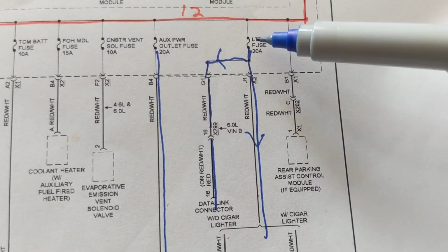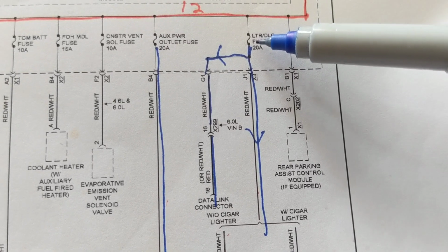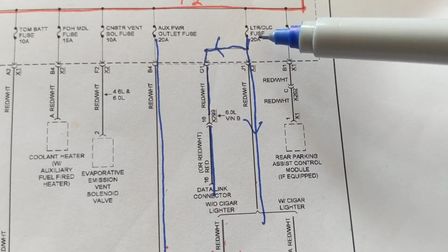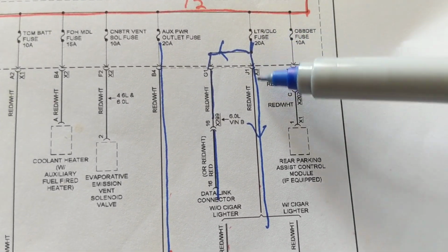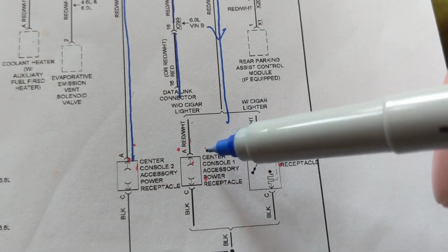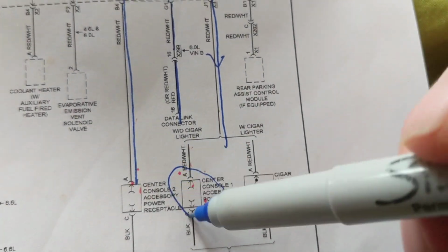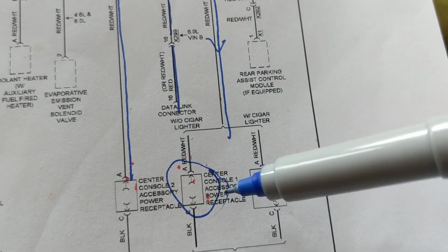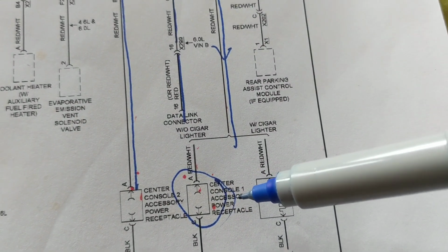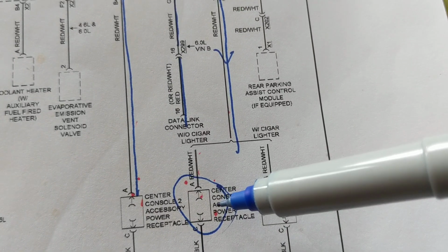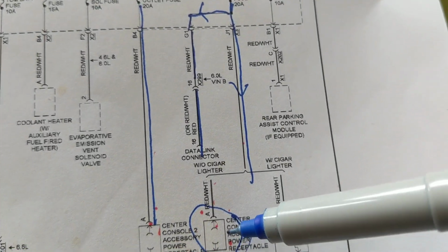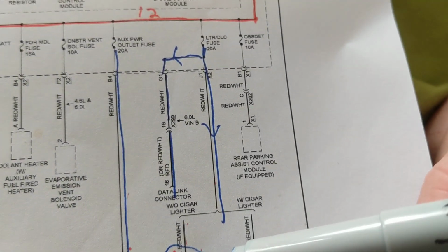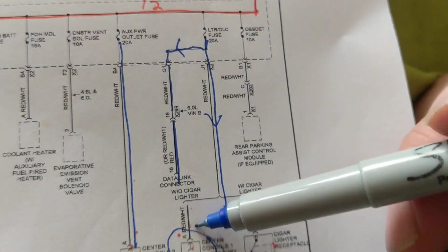When you have a problem like this, and you want to know if it's the fuse, and you have the schematic in front of you, you see if there's anything else connected to that point. We're dealing with this point, correct? This is the problem. I went to measure at this receptacle. I did not measure 12 volts. I measured 0. So obviously I know there's a problem. That's why obviously the charger is not working.